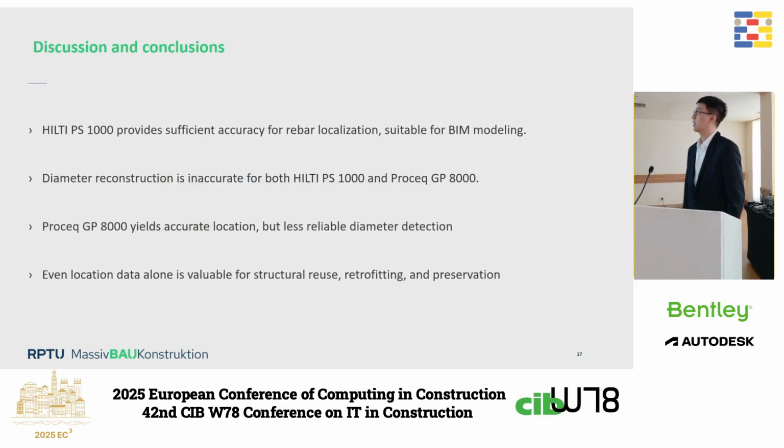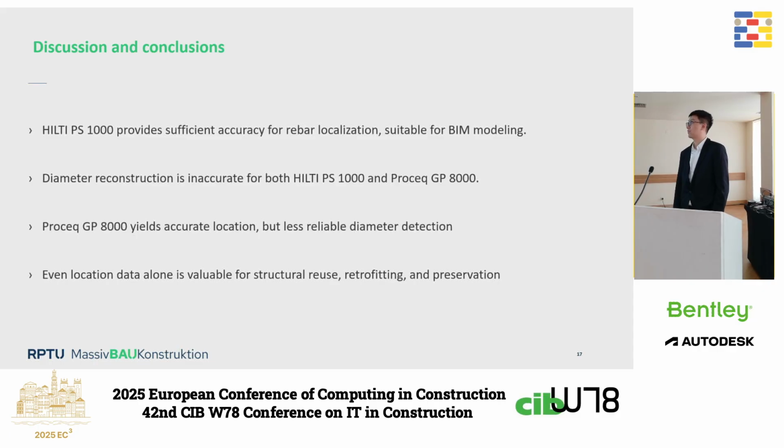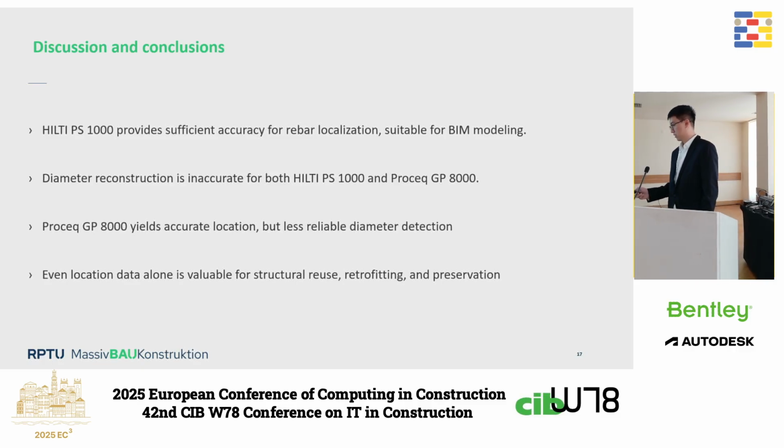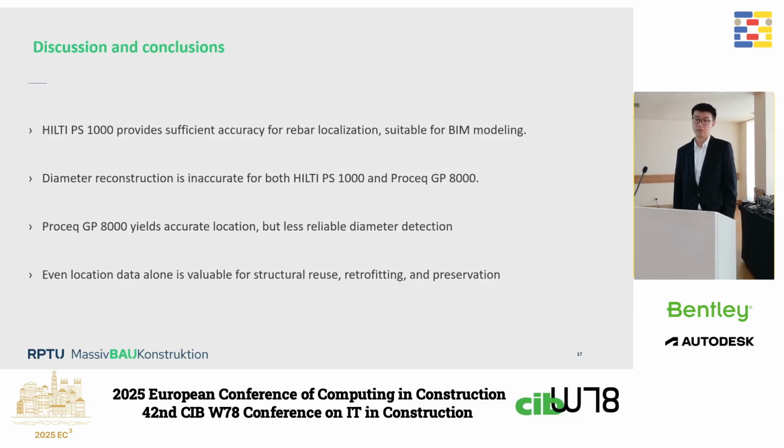Firstly, in our study, the PS1000 provides sufficient accuracy of the rebar localization, or rebar position, and this is suitable for the Scan-to-BIM workflows. But diameter extraction is inaccurate for both devices, and the Proceq GP8000 is okay. It also performs well on location extraction, but it has less reliable diameter detection.